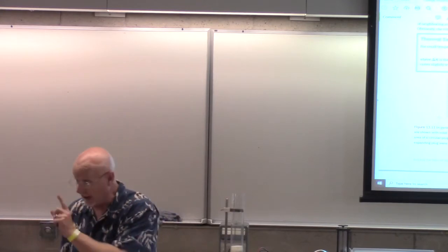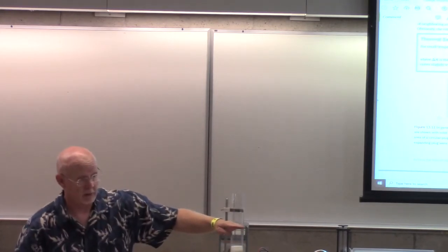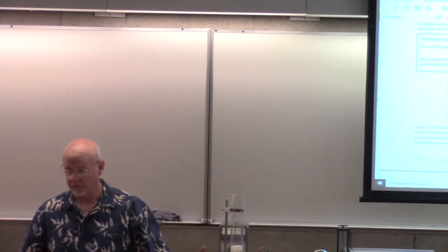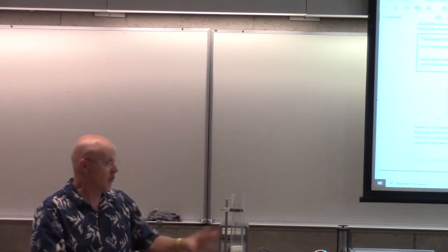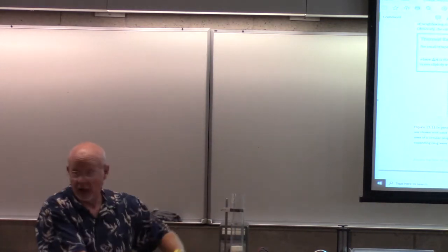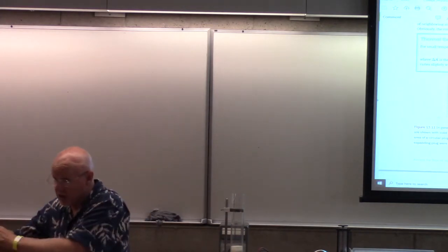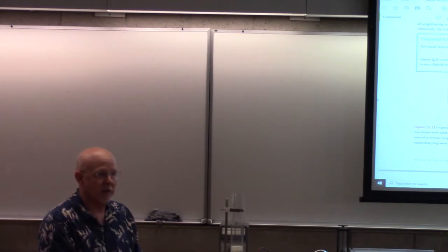And so if I look after I've been driving for a while, that level has now gone up because there's more volume. And so what I'm interested in is the volume of that. And of course, the reason you put it in a little airtight, vacuum-sealed container is because then when the car sits in the parking lot and cools down, it'll create a siphon and pull that back into the radiator.